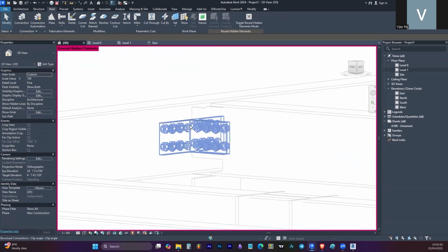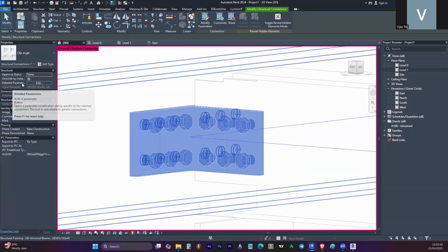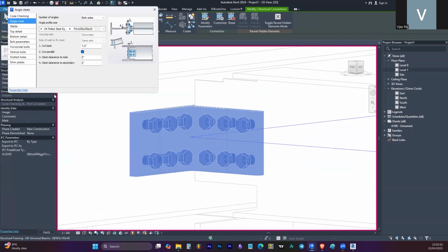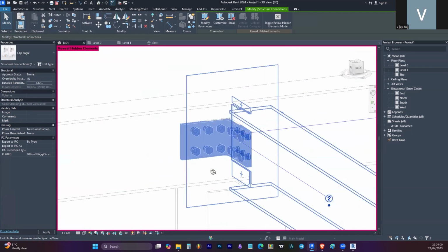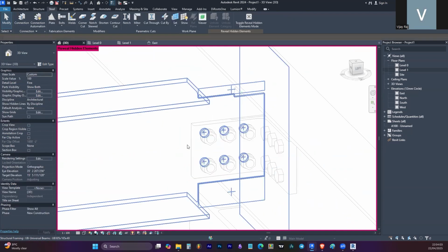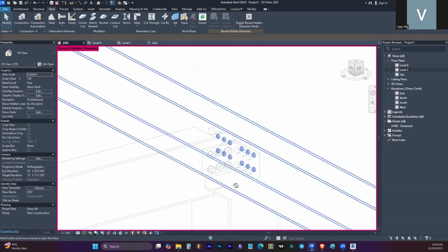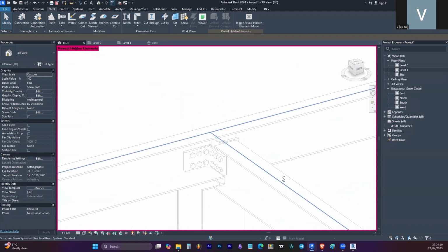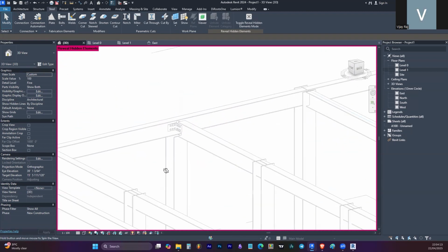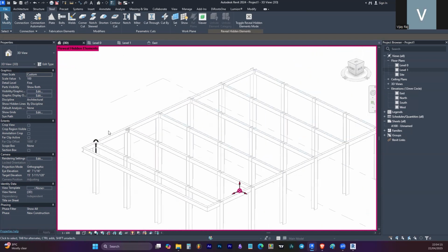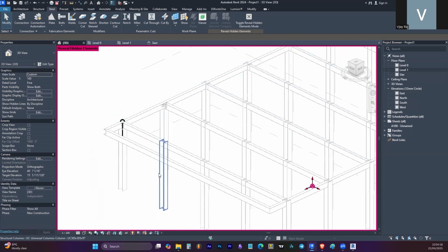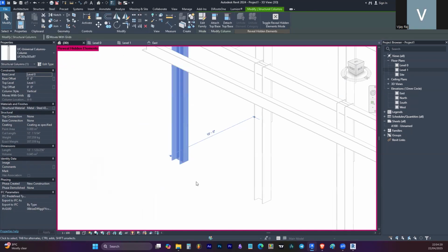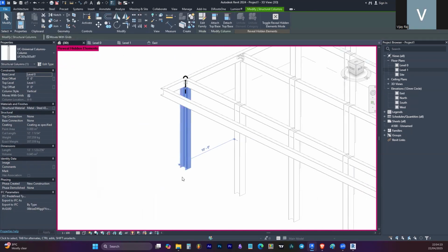So using this kind of options in detailed parameters, we can update how many bolts we want and how much the length will be, what the height will be, and the bolt nut and bolt thickness. Those details we can update with respect to those things. Not only this connection, also the column base plates and other elements involved in the project.